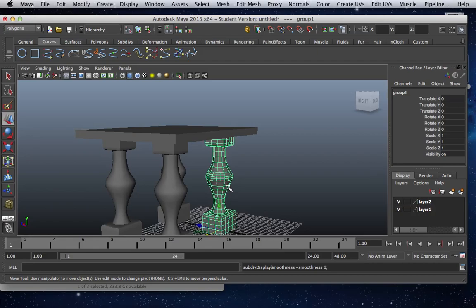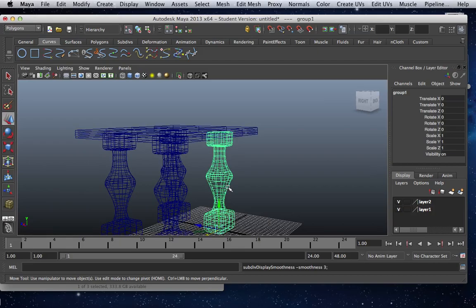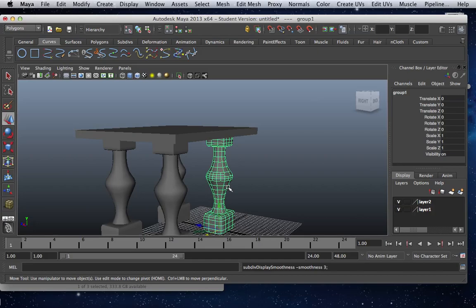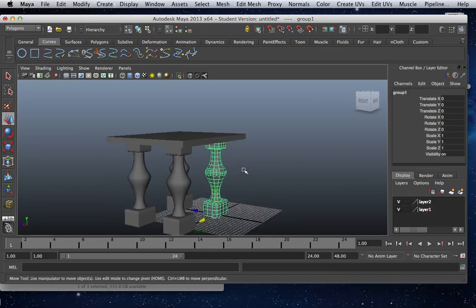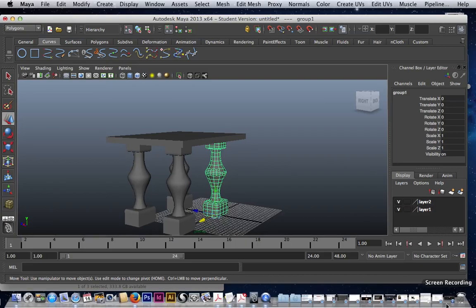From the 1 that is a straight polygon, to the 2 that is polygon and roundness mode, to the 3 that you see the roundy mode, and then 4 is wireframe, 5 is shaded mode, and then we have 6 and 7 that is with lighting and with materials. So keep that in mind. All right, this is the table for you.